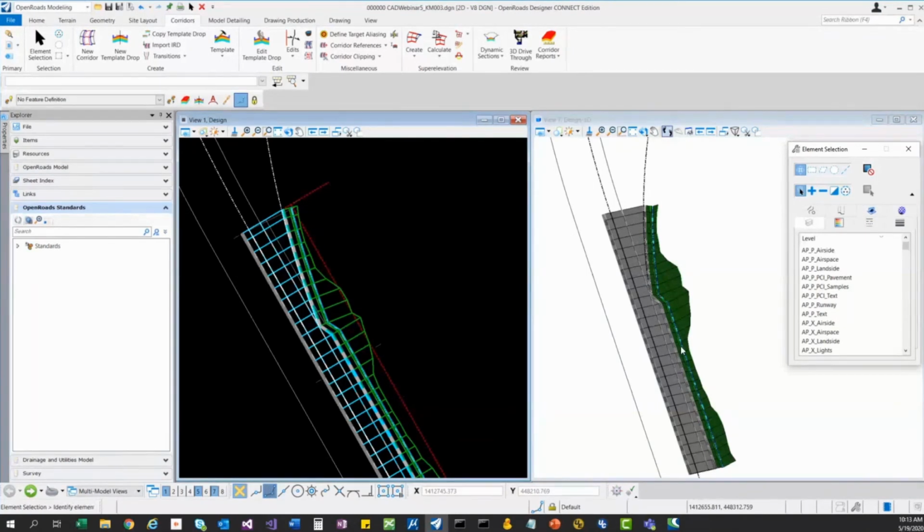So there's a couple of different things you can do. One thing you could do is make it slide over to 0 so that it just doesn't draw in. You could do that with point control, or you could do that with parametric constraint. We did point control over here, so let's do parametric constraint.